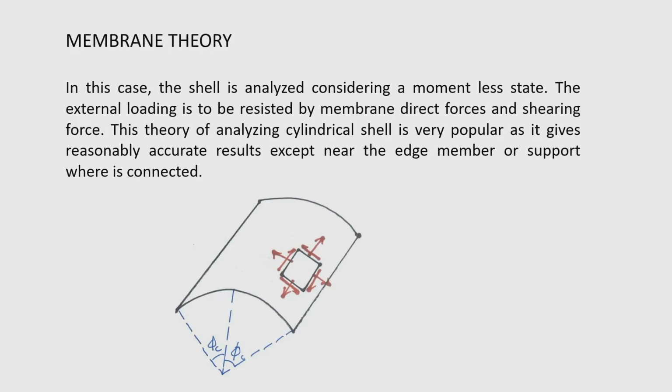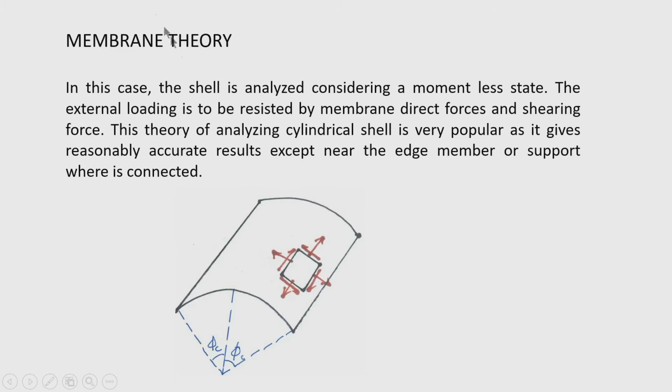Then the membrane theory, which we will discuss in today's class, and our whole analysis will depend on membrane theory. In the last module, I will introduce the bending of the shell. So, in this case, the shell is analyzed considering a momentless state. That means the bending rigidity of the shell is neglected. So, what does it mean? That the shell element is in a state of in plane forces. So, in plane forces are the only resisting forces in the shell to the external load.